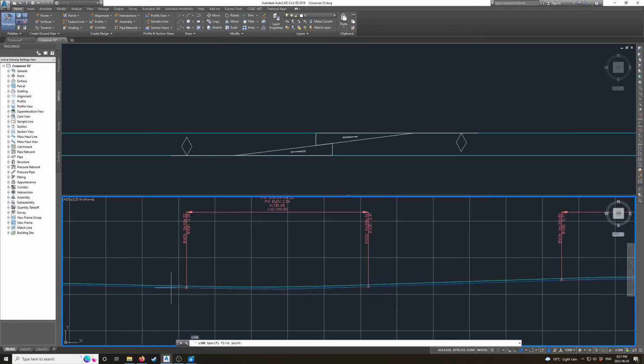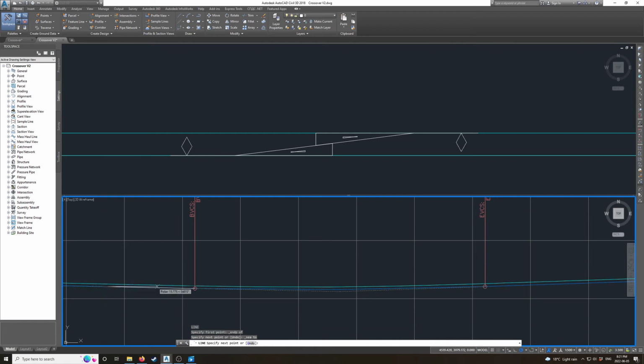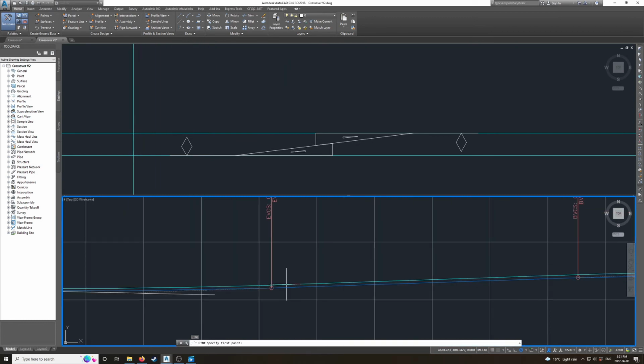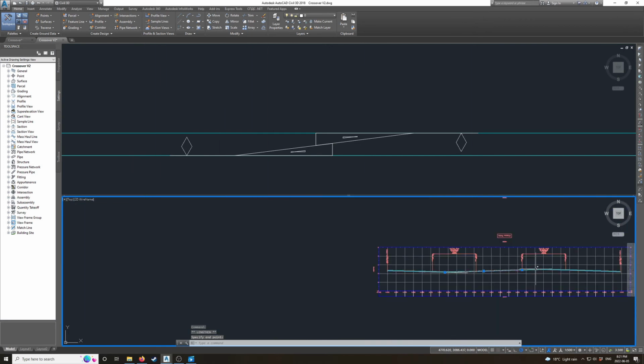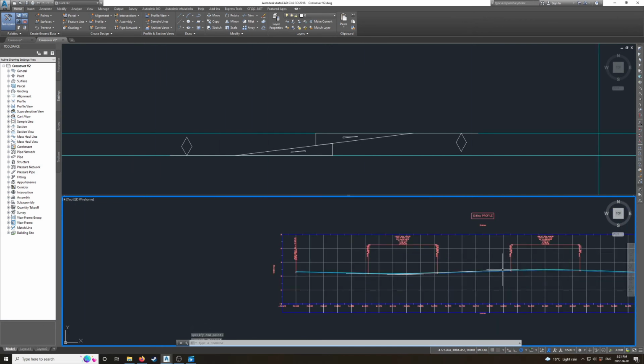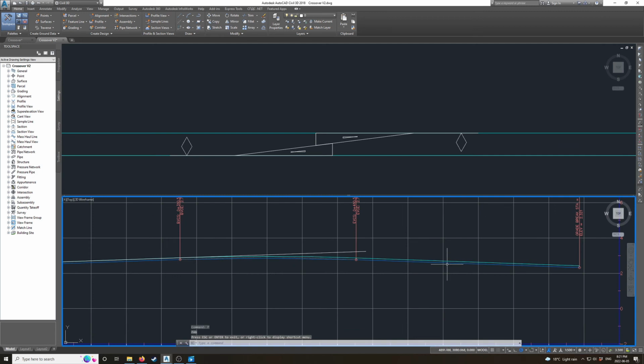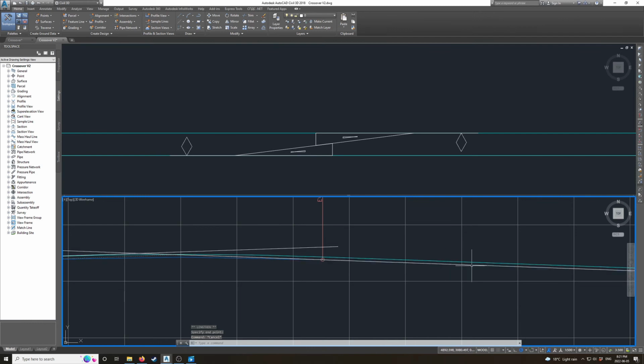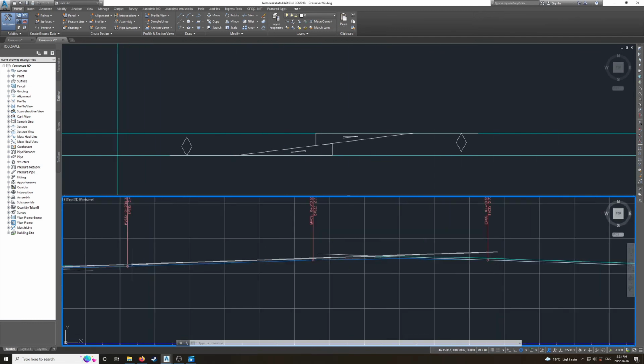So what I will do is make the dark blue line match up with the cyan. So over here, we're gonna come in at the same grade and elevation of the siding, but I want it to match the main line grade and elevation through this area where we're proposing to have the crossover. So we'll do something like this. I'm drawing some lines so that we can figure out where the vertical PIs are. And over here, we want to continue with the siding profile. So notice that in this area, we're still matching the siding, but in this area, we're matching the main line.